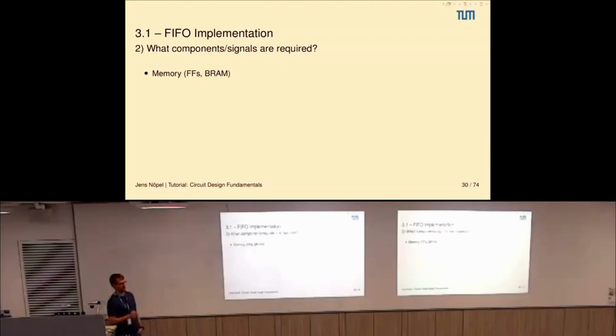It should definitely be one that is on chip, because your FIFO implementation should also run at the same frequency as your module or modules. That's why either flip-flops or BRAM. BRAM is like SRAM, but in a block-ordered manner, and this is the special term for FPGA SRAM that contains only data.